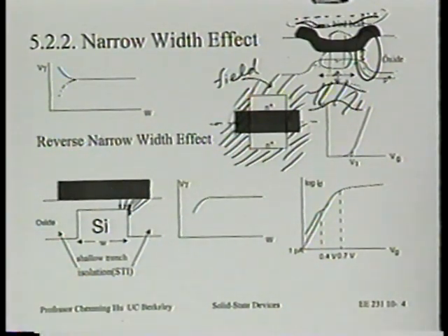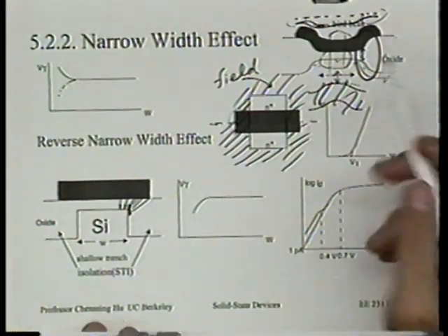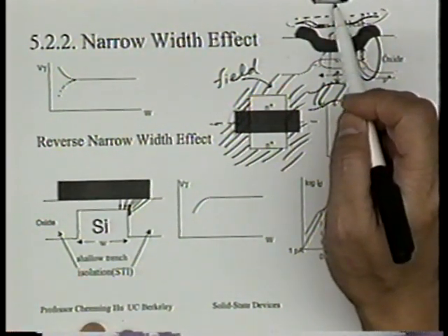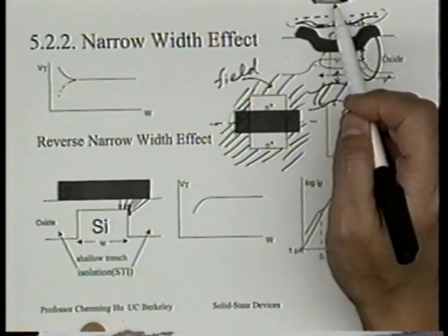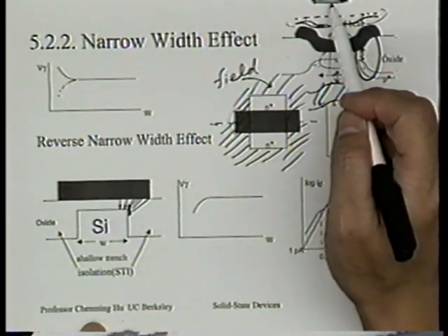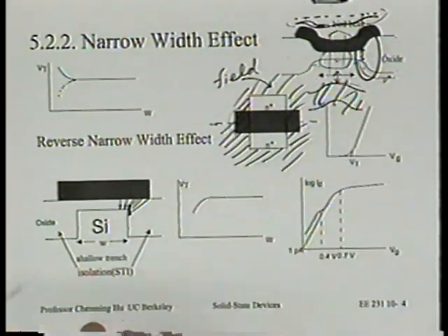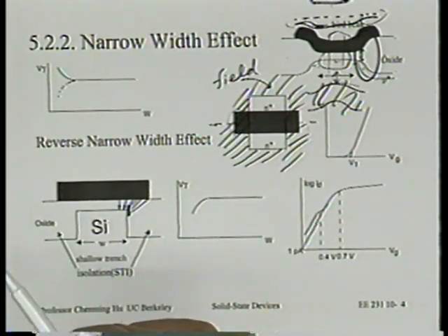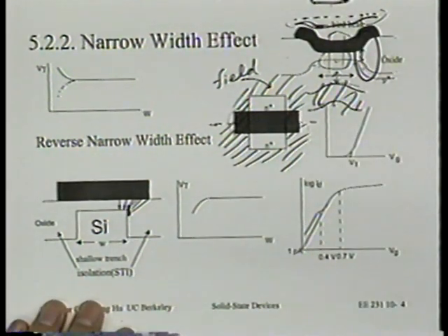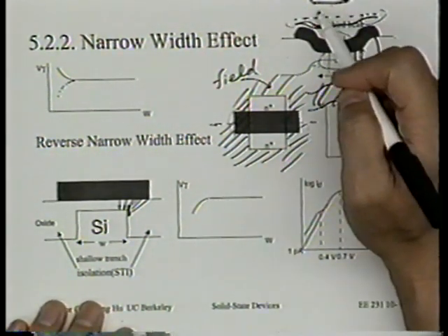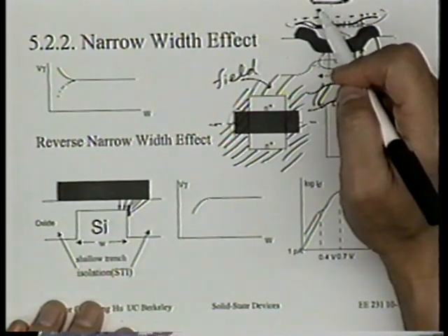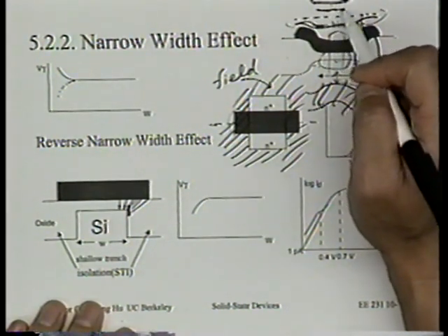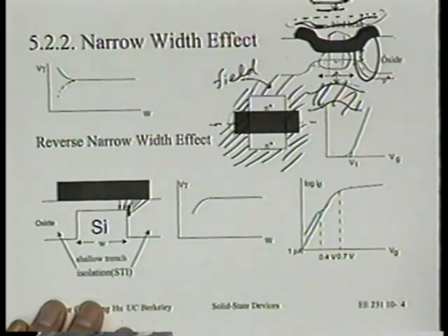However, at a certain voltage very close to VG, let's say, we start to apply a positive voltage in an attempt to lower this value. We're going to try to pull EC close to the Fermi level, EF. Is that correct? We're trying to do that, okay? So now let's visualize with me. When you apply a certain VG, you succeeded in lowering the EC lower here. Got it? Yes? What about this part?